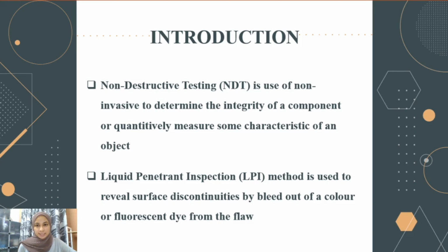Non-destructive testing is used non-invasively to determine the integrity of a component or quantitatively measure some characteristics of an object. The liquid penetrant inspection method is used to reveal surface discontinuities by bleed-out of a color or fluorescence dye from the flaw or defects.